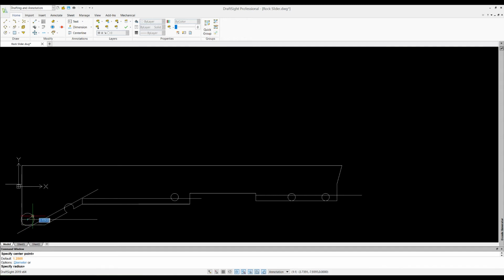And then our holes, let's make them 1/2 inch, so 0.25 radius, and we'll do that. We may as well just put one right there on that intersection. We'll just eyeball one in there. Okay, that's the midpoint of the line, so that'll work fine. That looks pretty good there.